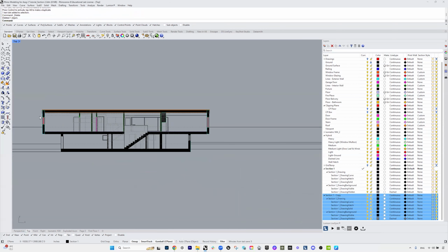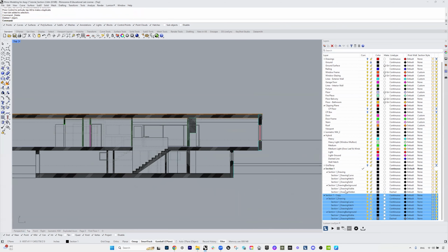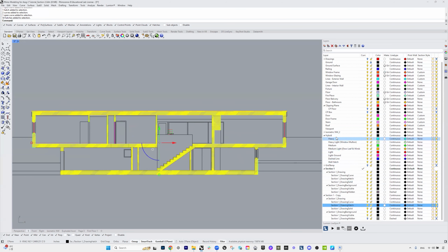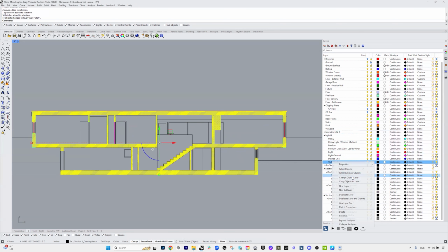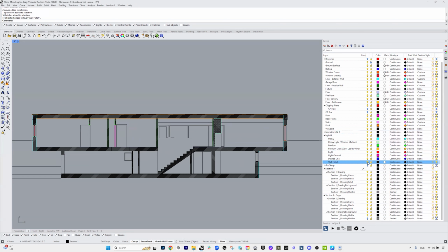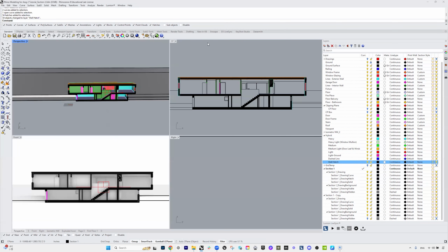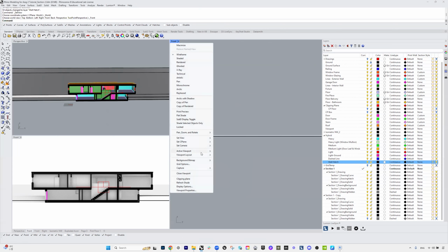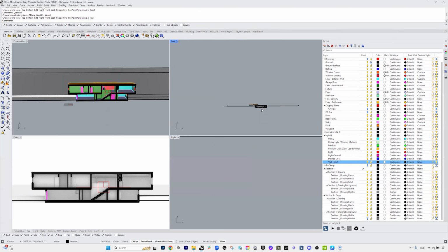And now with this, we can start assigning the line weights. The first thing I can do is probably select this hatch over here and select object. And I'm going to move that to this hatch layer over here, change object layers. So I'm going to turn that off to make sure that's over there. And then I'm going to double click on this view over here. And this view really should be top view.